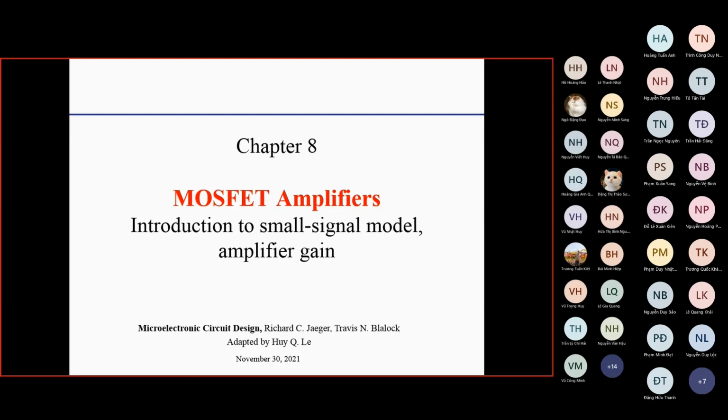So for field effect transistor, we don't have an input characteristic curve because at the input we have only the voltage between the gate and the source, VGS, and the current at the gate, IG, is nearly equal to 0. So for BJT we have three important characteristic curves. At output, the most important one is the output characteristic curve. At the input, you have the input characteristic curve, and the relationship between the input voltage VBE and the output current IC, you have a transfer characteristic curve, right?